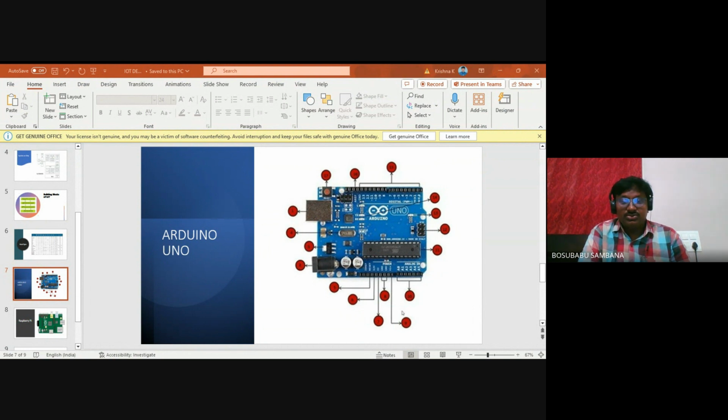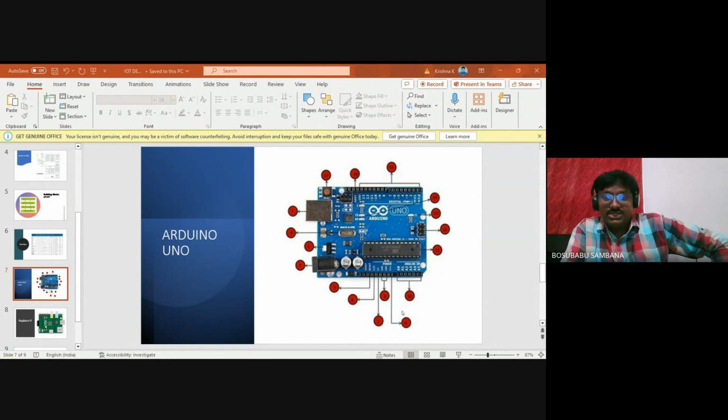Here we are going to take a look at one particular example, Blink. It gradually activates and deactivates the LED. Choose one case study from the available options. Selecting the correct Arduino board name, which corresponds with the board connected to your computer, is essential for a successful upload of your program to the board. Select your board by clicking Tools, then Board. Our tutorial assumes that you will be using an Arduino Uno, so we have gone ahead and given it that name.